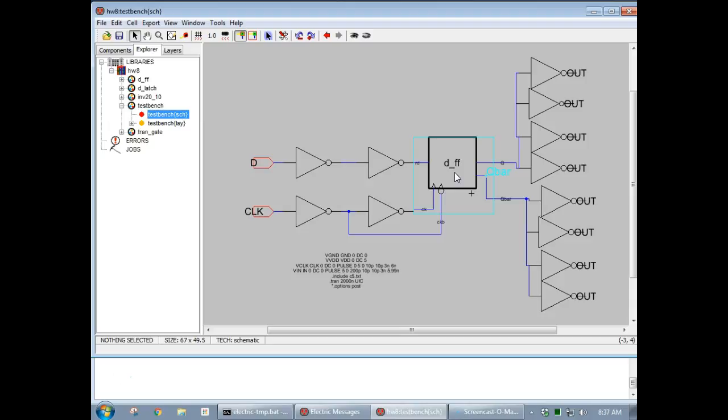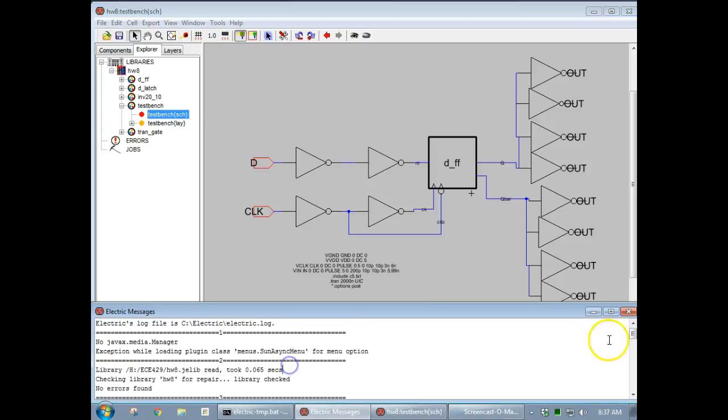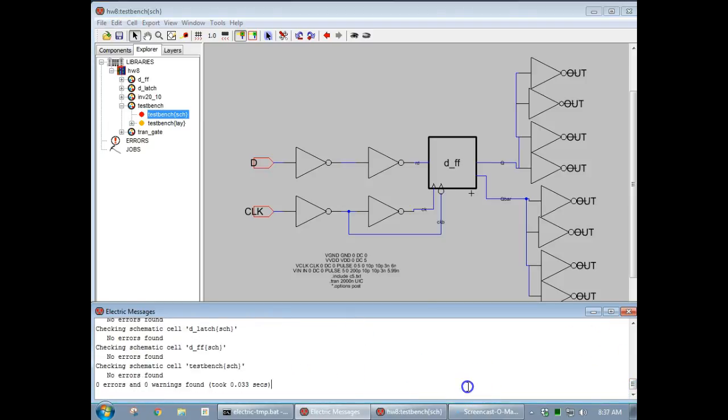Because otherwise you make sure your schematic works fine, and then if you test your layout under different conditions, it's basically not valid to compare your measurements, and it's not consistent. So here we go. First we're going to run the simulation on here, but before we do the simulation, we always run DRC. DRC, zero errors. That's what we want to see.